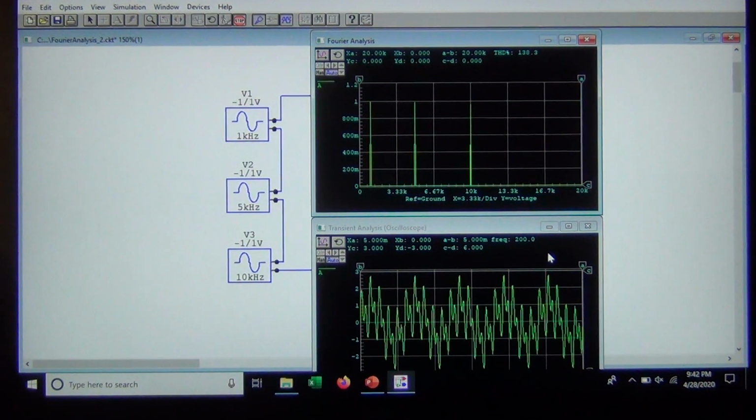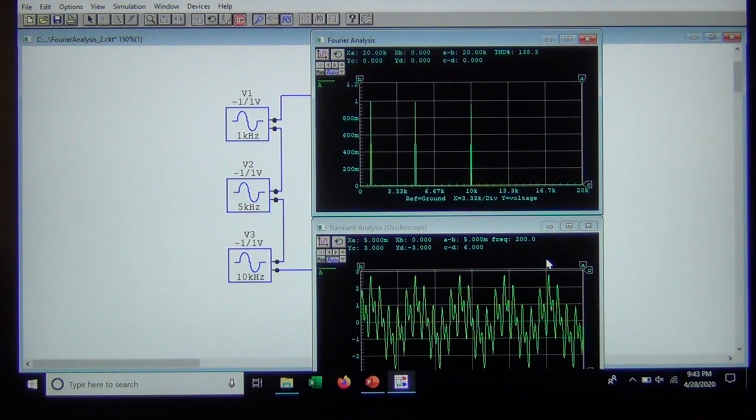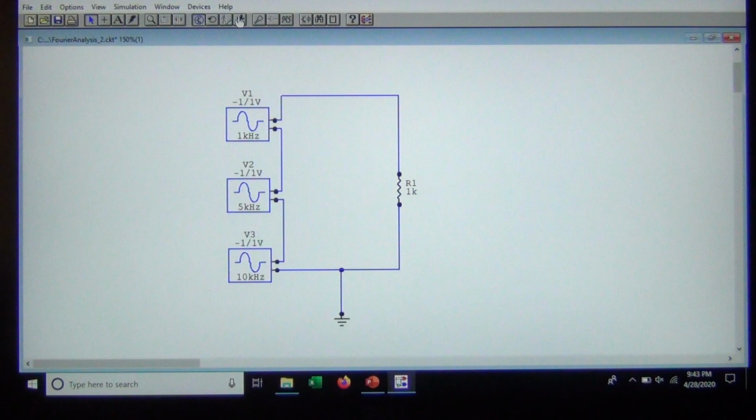I'll go back to this. So again, it turns out we can actually see exactly what's there with the spectrum analyzer. And not shown here, but we can see small signals in the presence of large ones. We cannot do that with the oscilloscope. The dynamic range of an oscilloscope or the time domain display is too small for that, or rather, is not very good for seeing that.